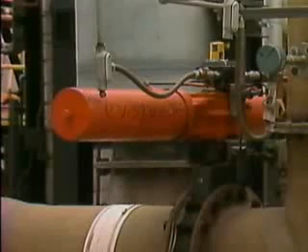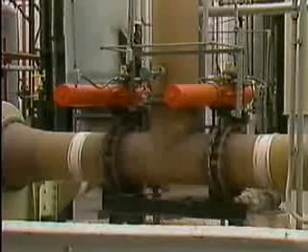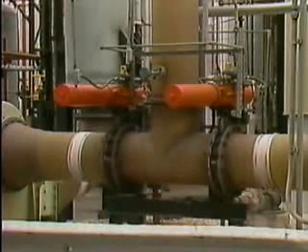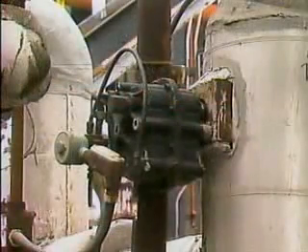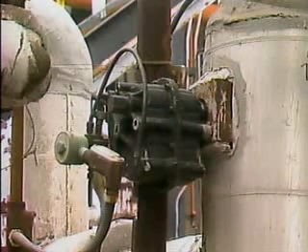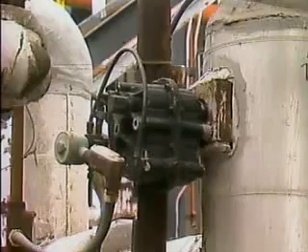A piston actuator is a pneumatic operator that uses a piston inside an airtight cylinder to position a valve. It's generally more suitable than a diaphragm actuator for jobs that require relatively long stem travel or more force to position a valve. A vane actuator is a pneumatic operator that uses air pressure against a vane or paddle to position a valve. This type of pneumatic operator is used primarily with ball, plug, and butterfly valves.